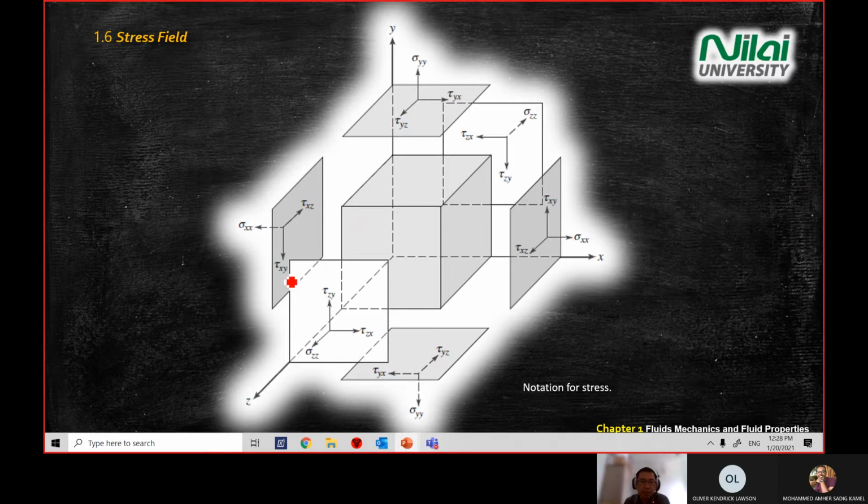Then same with the shear stress xy. Shear stress xy, again in x-plane, y direction, and the direction is opposite to the right hand side to balance the cube. So if the direction is not balanced, then the cube will rotate and experience deformation. So it will be the same for the other planes also. This one will take some time to study.